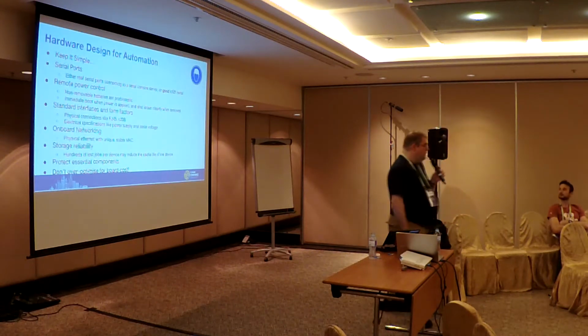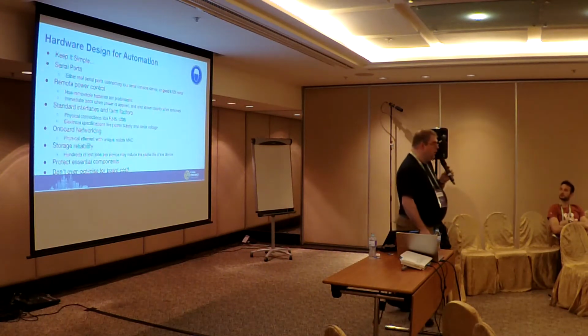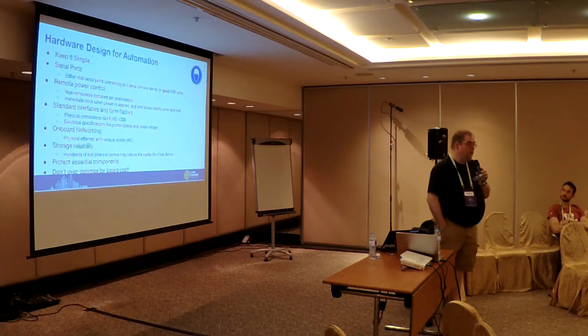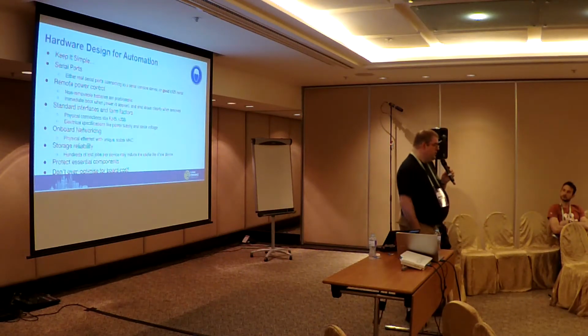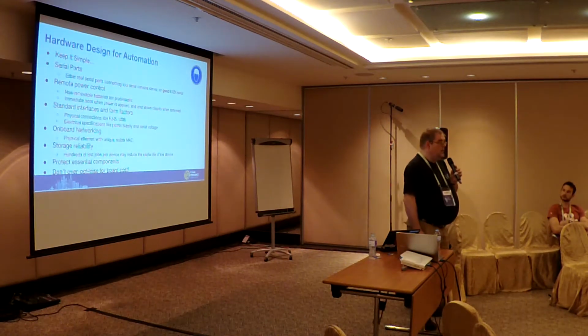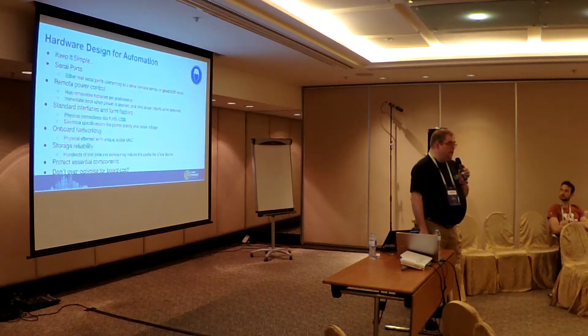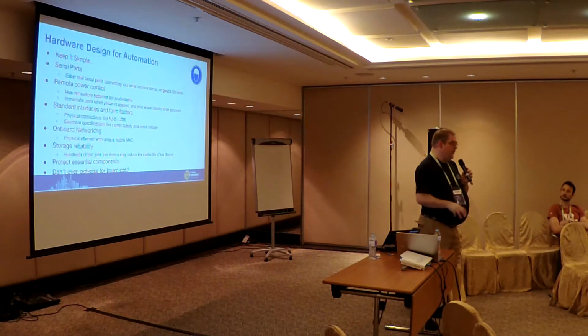We also want to have immediate power, immediate boot when we apply power. If we have to push buttons, if we have to fight with a battery, this is more complexity. Please, and again, this is not necessarily what you want for a customer-facing device, but if you want something that is going to work in an automated testing solution, have it boot the moment you apply power. It's the right answer.